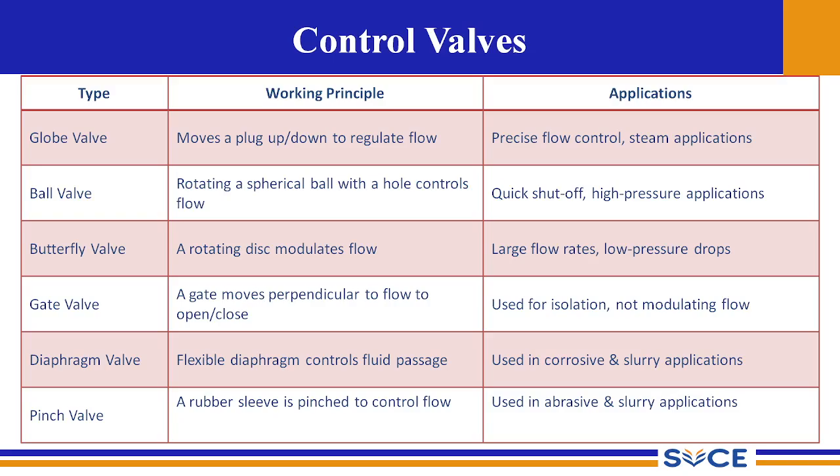Diaphragm valve. The diaphragm valve has a flexible diaphragm, an elastic membrane kind of arrangement, where the diaphragm is stretched or loosened to control the fluid passage. It is used in corrosive applications and to transport viscous fluids like slurries. And next is the pinch valve.